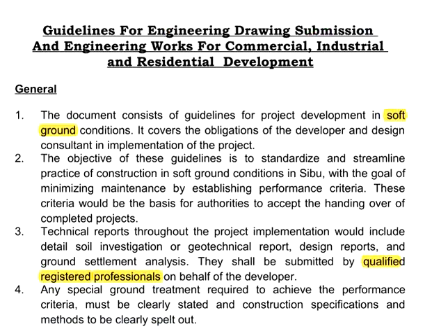Next, let us talk about some design issues related to soft ground conditions, as this may be a problem to areas with soft ground, organic soil, or peat. One of the greatest issues about soft ground will be settlement. Settlement is something that we do not like, as this can bring harm to the structures if not properly catered for, and excessive settlements may bring in other issues, both during the construction and after the construction.